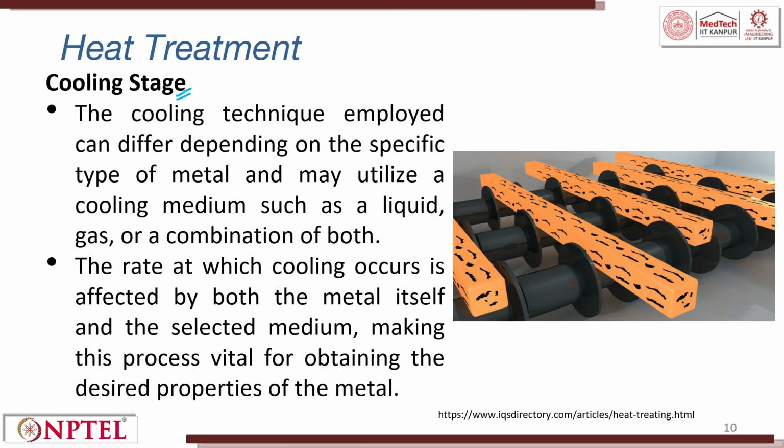Cooling stage. The cooling technique employed can differ depending on the specific type of metal and may utilize a cooling medium such as liquid, gas or a combination. For example, many times we take a bath and fill it up with liquid. This can be water or oil. So, we quench the material.